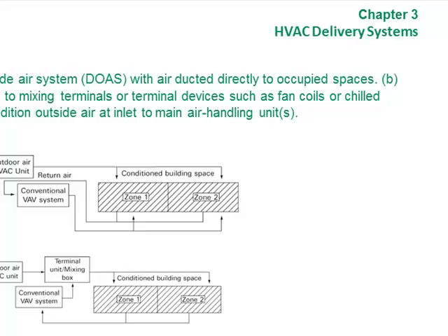Well, you would use that in a house. So let's say it's an office building. What would be the most energy efficient? Variable air volume duct terminal. Well, the variable air volume, or VAV system, is the most energy efficient because the fan only works when it's needed, and that's what sucks up the energy.